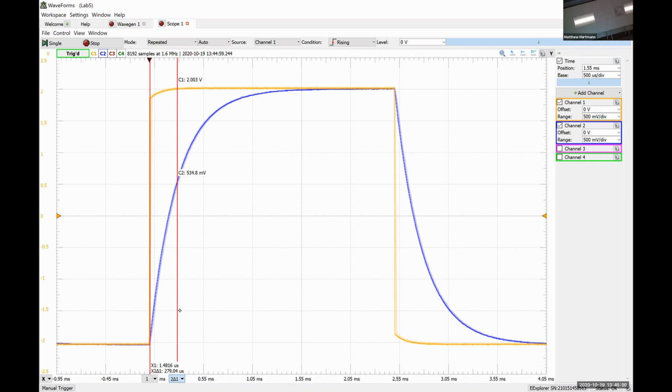So our next step is asking us to calculate the voltage at exactly 1 time constant, okay? So at 1 time constant, the ratio of t over tau should be what? Right, because at 1 time constant, if t is equal to tau, then tau over tau is 1, right?